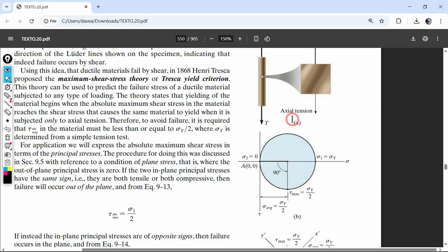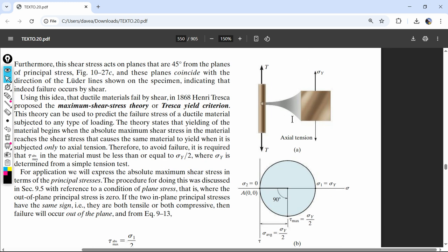And so that's exactly what I just said, so that's probably true. All right, so this is a state where these are your principal stresses. On the Mohr circle, we're at the biggest compressive or, in this case, tensile stress. It's positive, so that's the biggest tension. And then the other principal stress is 0 because there's nothing in that direction.